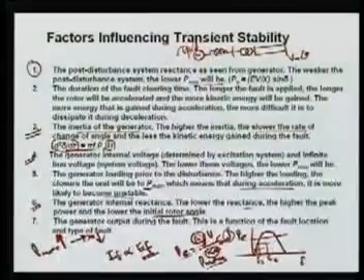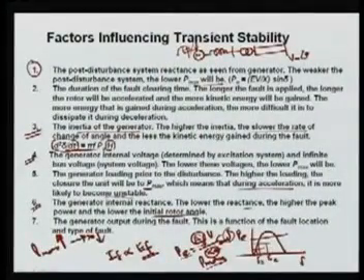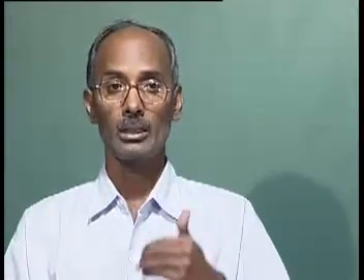So normally we go for a compromise on X here, and this X is also very important while we are calculating the reactive power, because the reactive power is directly related to this X, how much loss in that system, because I square X is the reactive power loss. So on one hand, if X is less we are more stable, but if X is more, what is happening? More reactive power and less fault current. If this X is less, the fault current will be more, that is not desirable. So again we have to go for a compromise, to decide which value is suitable.